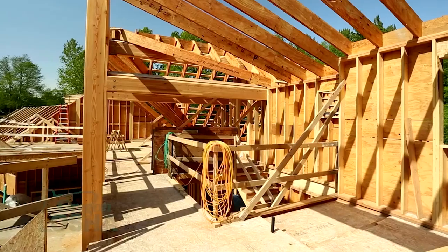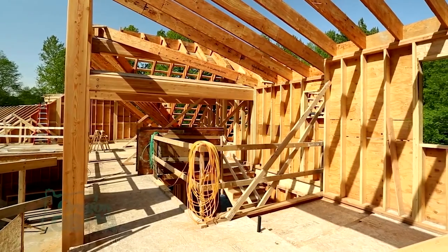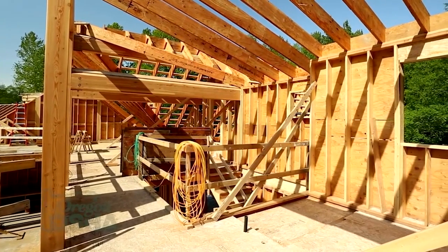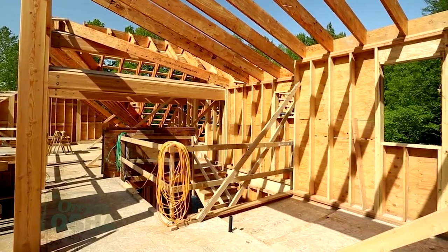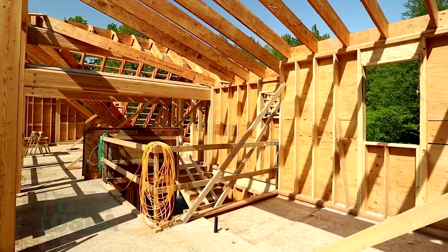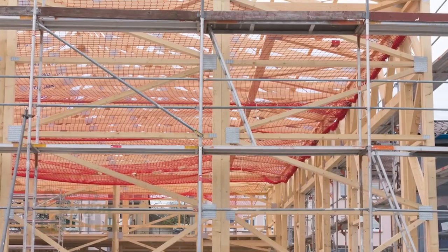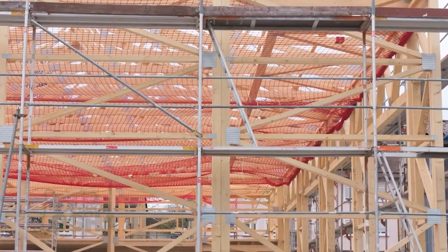Are there things that we can bring in instead, for interior falls, instead of trying to tie people off and keep them from falling towards the interior? We use a lot of guardrails once we're framed up on the exterior walls to create protection on an exterior fall, but we still have falls a lot of times to the interior of the building. Are there ways to fill that void with something so that we don't have a 6-foot fall, or if somebody falls, they fall into or onto something like netting for the interior?